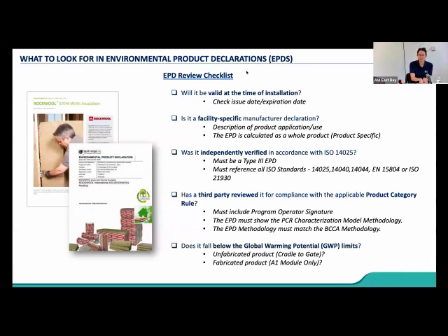This is going to be particularly relevant when you look at materials that are procured abroad, right? Because if you have a different governing organization in China, for example, where you might have been planning on buying your steel from, that's going to pose challenges when you're trying to procure steel that's compliant for California. Generally, a lot of the PCRs that have been set by the state of California were made in conjunction with a lot of industry organizations that are focused in the United States, like the American Institute for Steel Construction. So just be really careful if you are planning on buying material internationally that those PCRs are exactly the same.